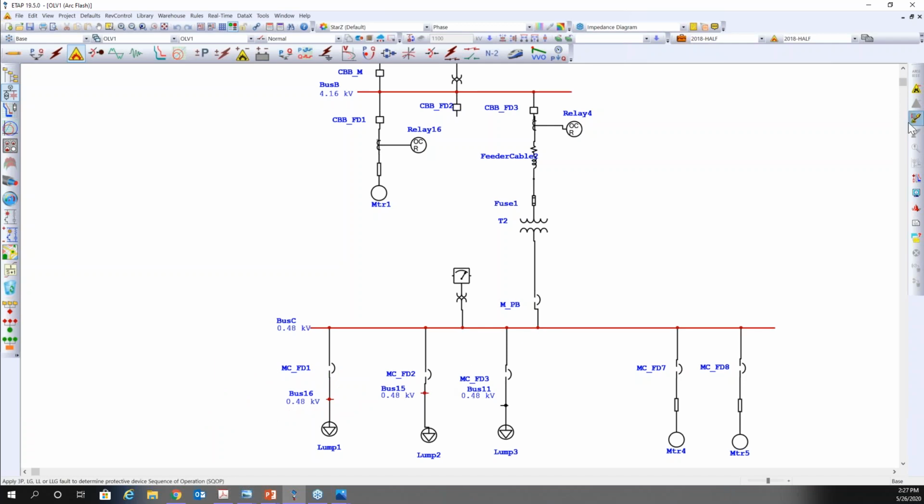Now, in feeder number 2, I've interlocked the light with the pressure. Obviously, the pressure is going to take an additional 9 milliseconds. So we have 60 milliseconds to clear the fault, and it's 4.228 calories per centimeter squared.